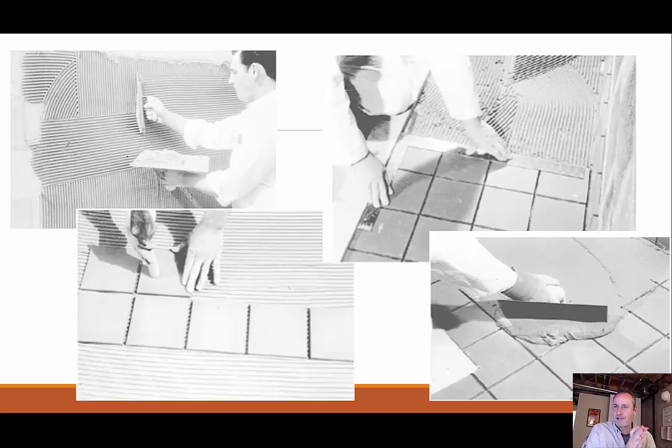So you end up with this suction. And if you've ever laid tile, if you put the tile against the wall, put some pressure on it to push it into place, and then try and pull it out, it does not want to come out. And that's not because your mortar has set, it's just because of the suction with the air pockets in there. So that's why we use this trowel with the little ridges to give me this pattern. But regardless, the first step, put on that mortar.